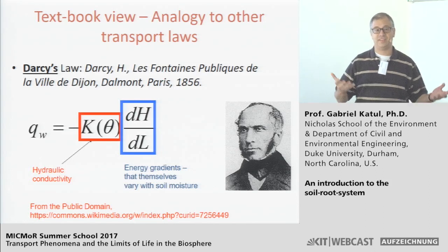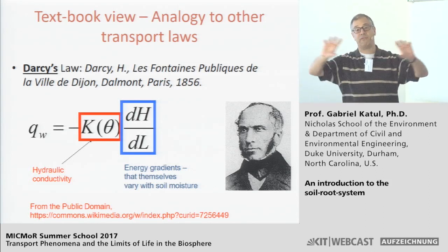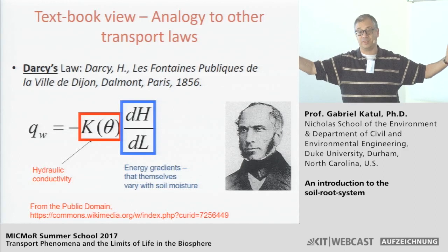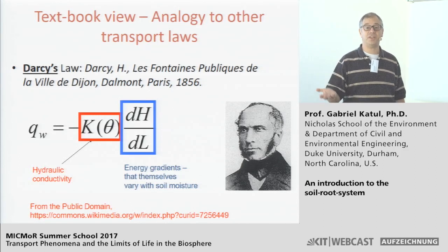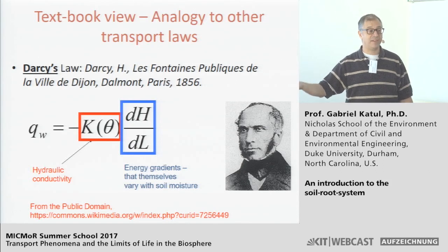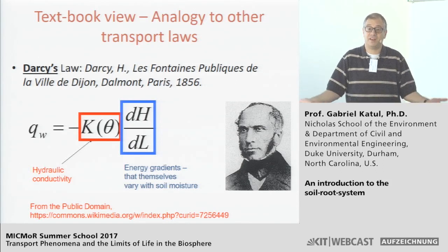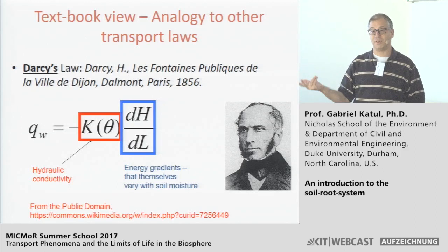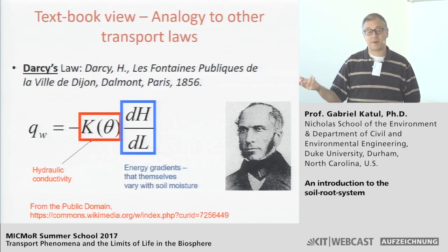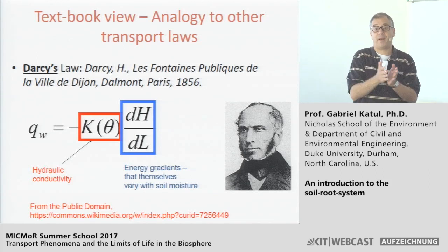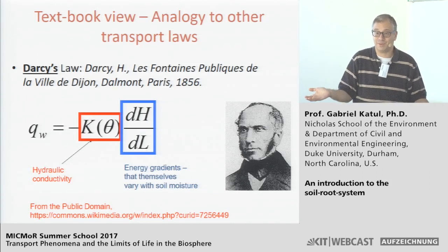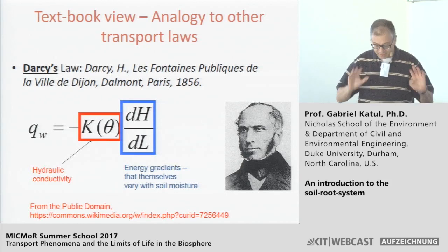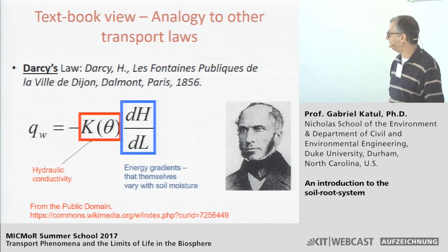The problem with Darcy's era is that a lot of the studies were done with uniform flows. The cross-sectional area of the pipe, the section that was used, or the soil column was constant, the flow rate was constant. So all the energy losses were typically either pressure or gravitational. There were no losses that are based on kinetic energy because the velocity was the same. So there was no way to think even outside the box and say, oh, these energy losses ought to be driven by velocities. They primarily assumed that if the head loss is described by a pressure potential and the gravitational potential, how would energy enter into the picture? Kinetic energy meaning, yeah? So some of these ideas were, so to speak, hazy at the time.